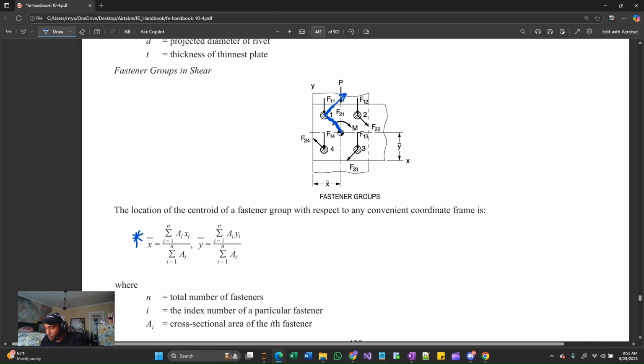Now, some people get a little bit confused on why we're taking moments of areas. Because this thing is constant in thickness, because density is constant in the flange, the thickness of each one of these area contributions is constant. Once we take out a density and a thickness term, all we're left with is density times thickness times area times gravity.